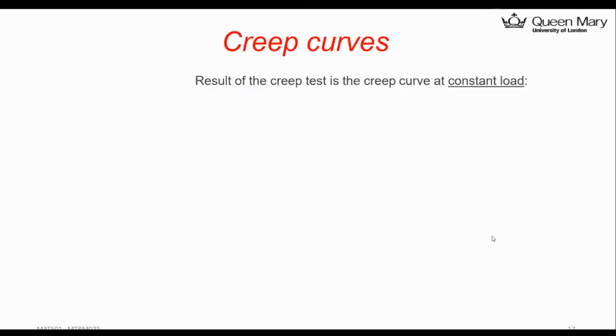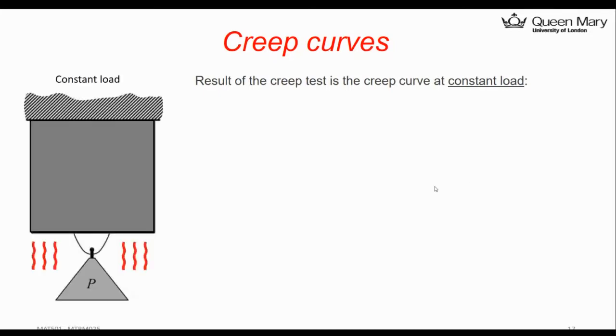And if we do a creep test, normally we can do that either at constant load or constant displacement. So in this case, we talk about doing this creep test at constant load at elevated temperature for a certain amount of time. So like this. Okay, I'm heating up the material and apply a load here.